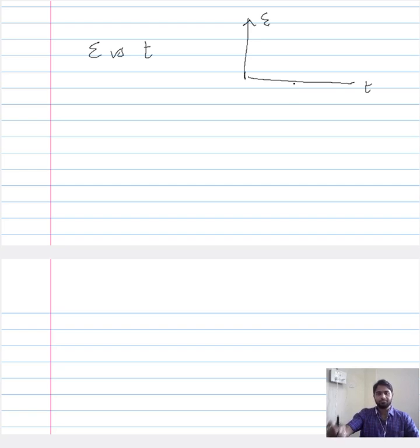So given that creep is nothing but the time dependent behavior of the material, that is what creep studies, this is being used as a conventional way of presenting the creep behavior of the material. While presenting the creep behavior in this framework, what we assume is that the mechanical load that we impose on the material is constant. Now one can ensure that the mechanical load is constant by applying a constant load all through the testing process.